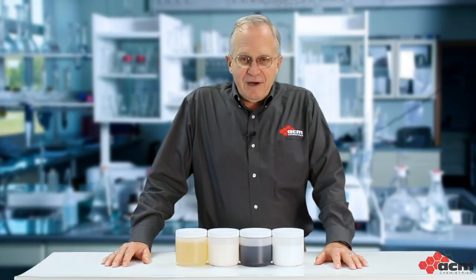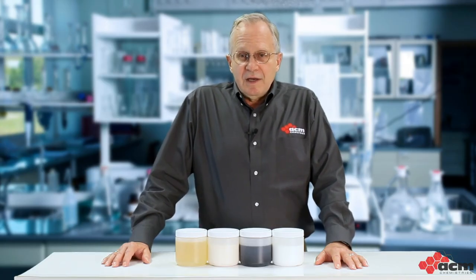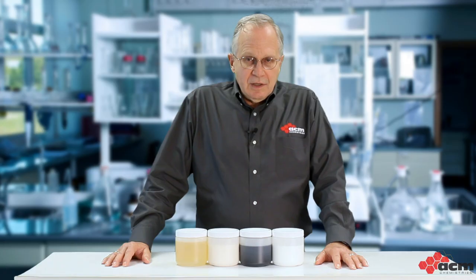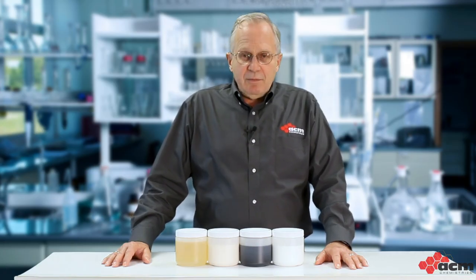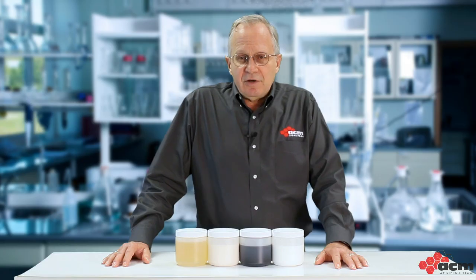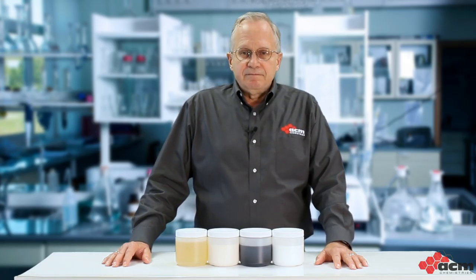Let's review what we've learned about admixtures. Dry cast admixtures are liquid chemicals that are added to the concrete during mixing. They generally allow us to reduce the cost of production by allowing us to reduce the amount of cement we may need, or improve productivity by increasing the amount of units we can make per hour. They allow us to improve the quality and appearance of our concrete and to overcome difficulties during manufacture. They also allow us to achieve properties that we cannot achieve any other way.